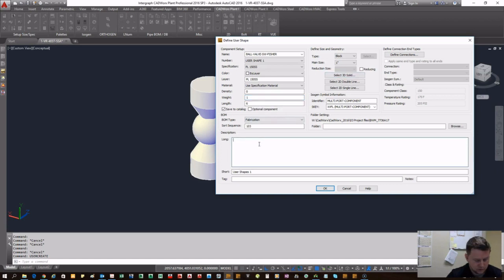We're going to put in a default description. Let's say in this case this is a specialty item, so we'll say SP-X spec, a generic way to reference the spec that's being used instead of having to write out the long description. SP dash. Now, the designer has the extra step that when they actually put this into the model, they will need to reference the actual numbers for that specialty item so that this is accurate.